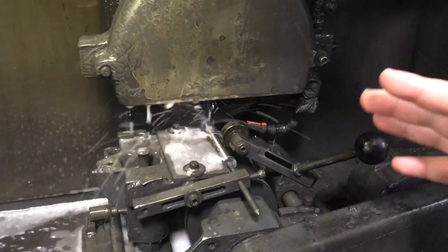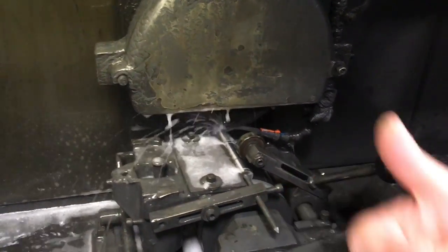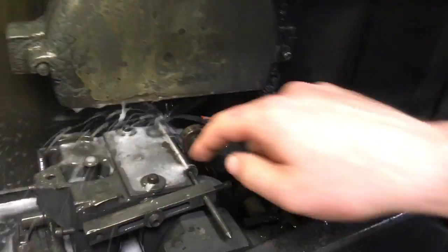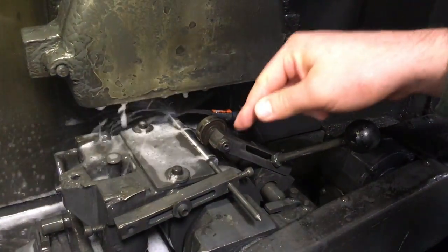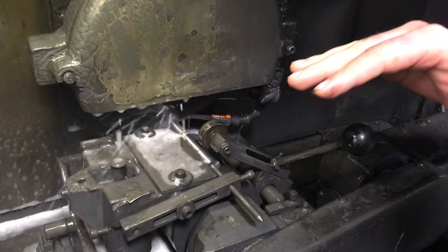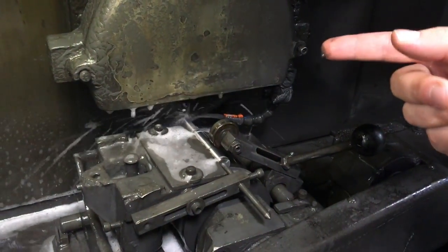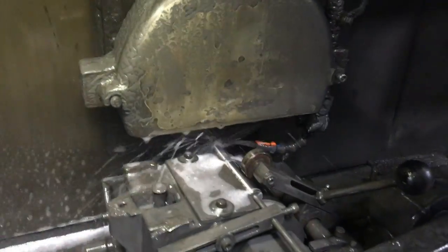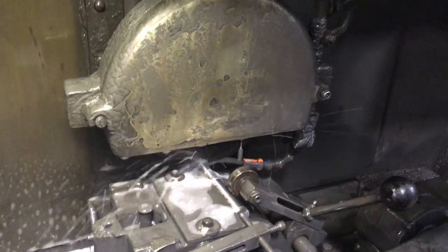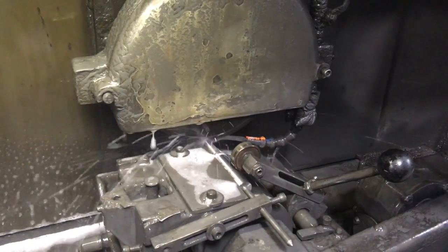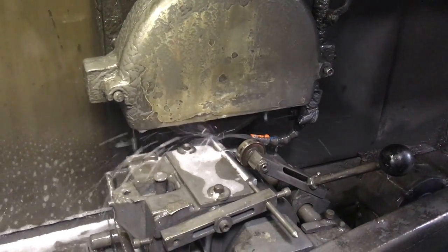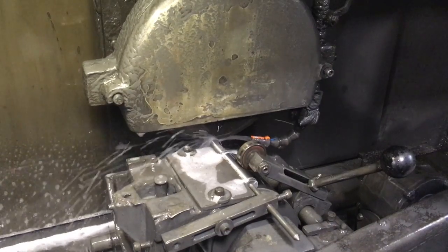We've got multiple support reactions here. We have a backstop that's holding the tool in place. We have a work blade here that the tool is resting against. We have a lever pressure on the tool with a bearing that's allowing it to rotate. The external force here is the grinding wheel actually grinding onto the material. So yeah, as evidenced by the next free body diagram over here.